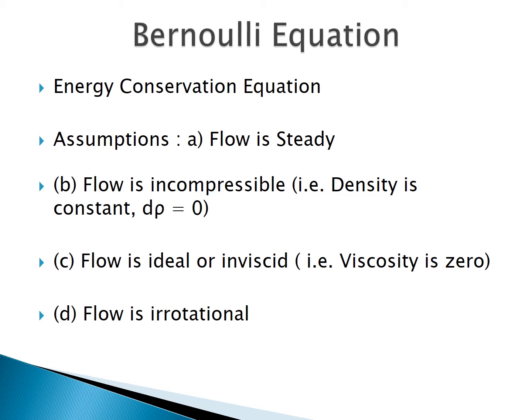And the fourth and the last assumption, the fluid is irrotational. By the word irrotational we mean that the net rotational change of the fluid particle is equal to 0. We'll see that omega z equals 0. We denote rotation with omega, so omega z in a particular direction is 0. So these were the assumptions of the Bernoulli equation.